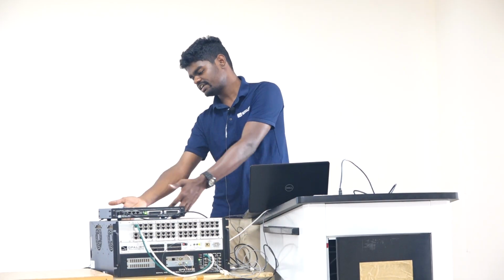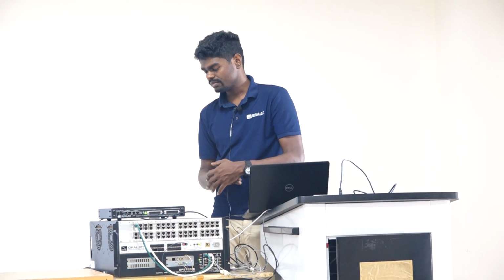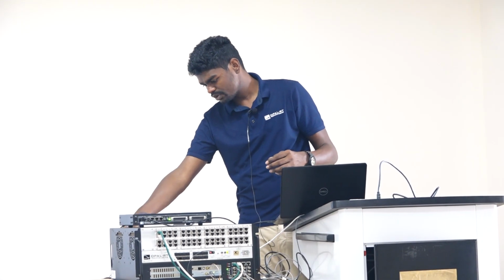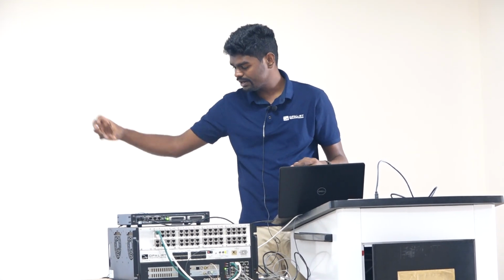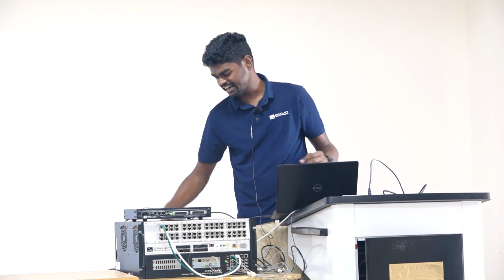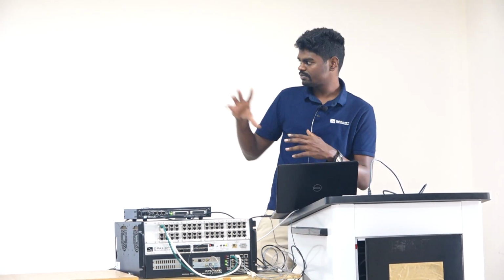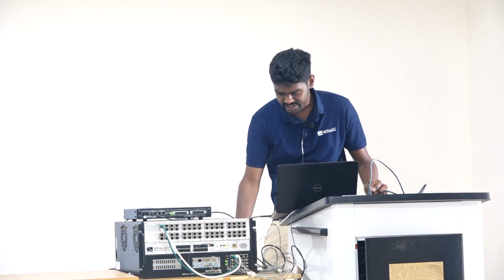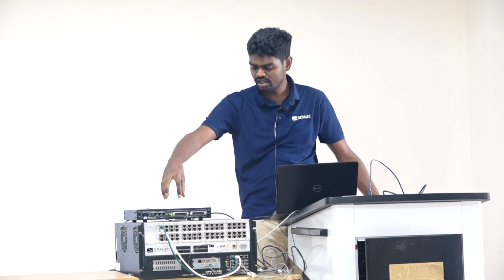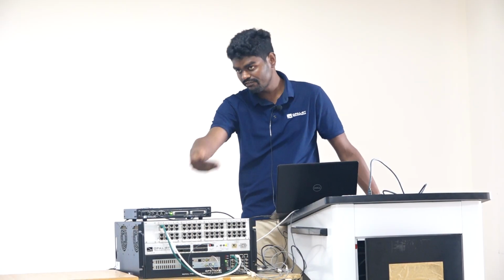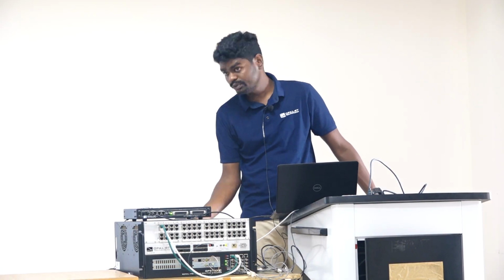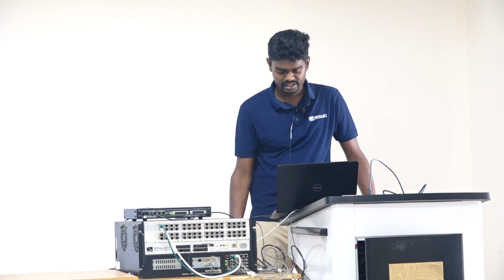On the back side of the simulator, we have the analog output. Maybe in the break you can come and see the connections once. From the analog output, I will connect all the feedbacks to the analog input of the controller through this connector. This is the analog output configuration, and in turn, after reading these signals, this controller will run the control algorithm and give out the PWM through digital output, which needs to be fed to the digital input of the simulator.